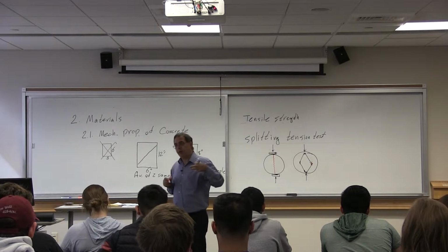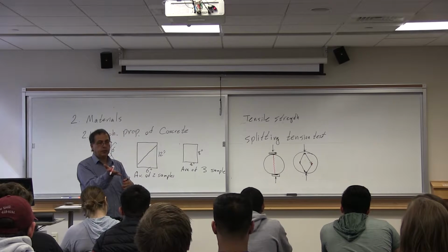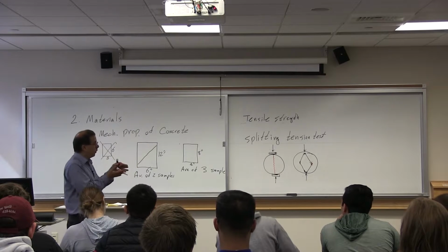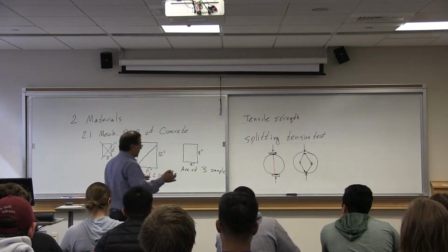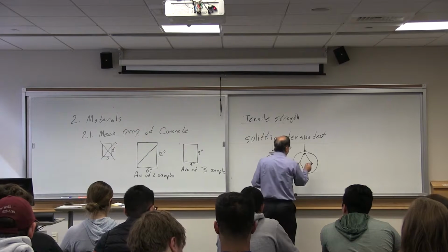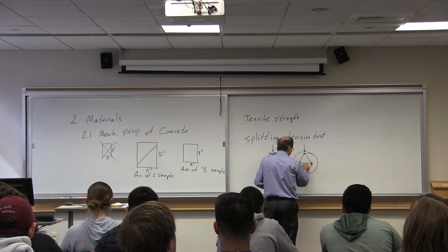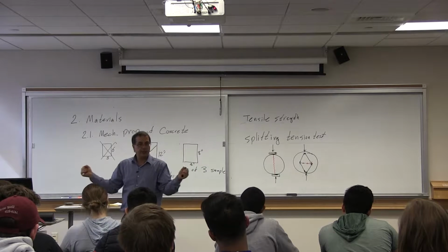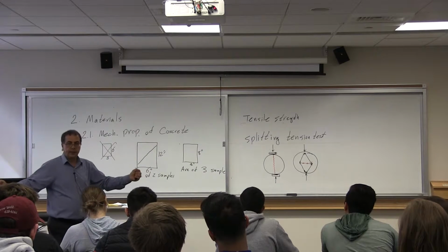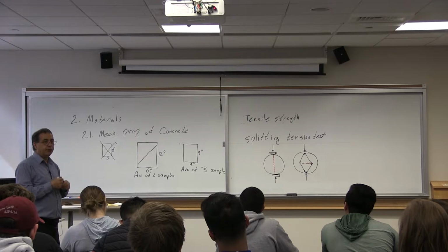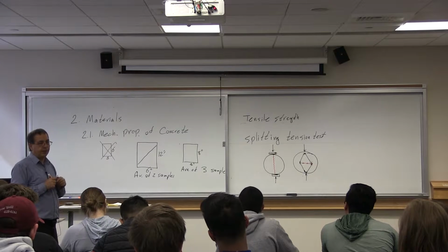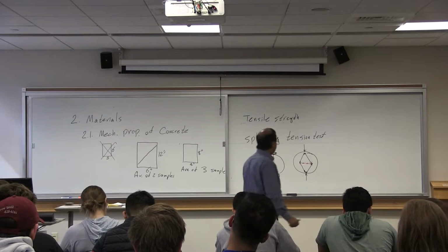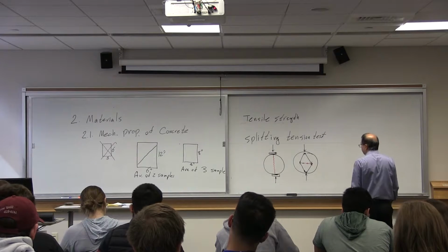The top force is pushing out, the bottom force is also pushing out. If you look at the horizontal direction, both of them have a horizontal component outwards. The only way you can satisfy equilibrium is if you pull them in. For that pulling in, the material in the middle would go under tension. That's a simple way to think about why tension would develop in the middle. So the load wants to transfer that way to bring it back in.